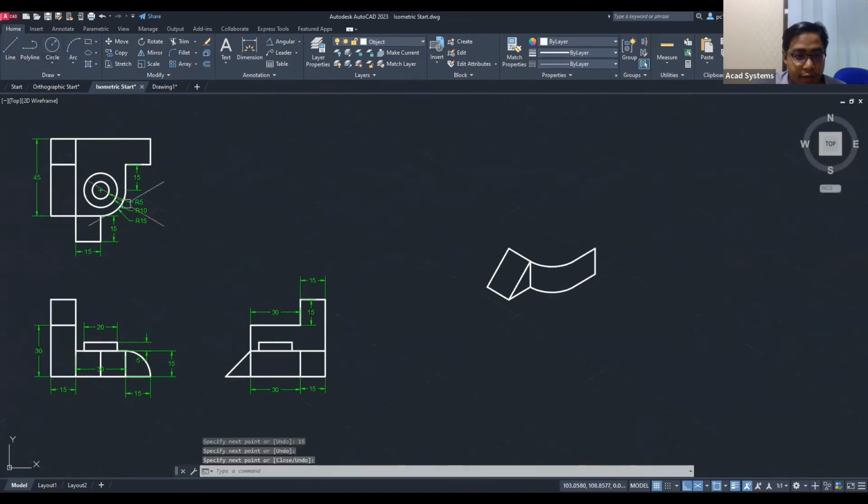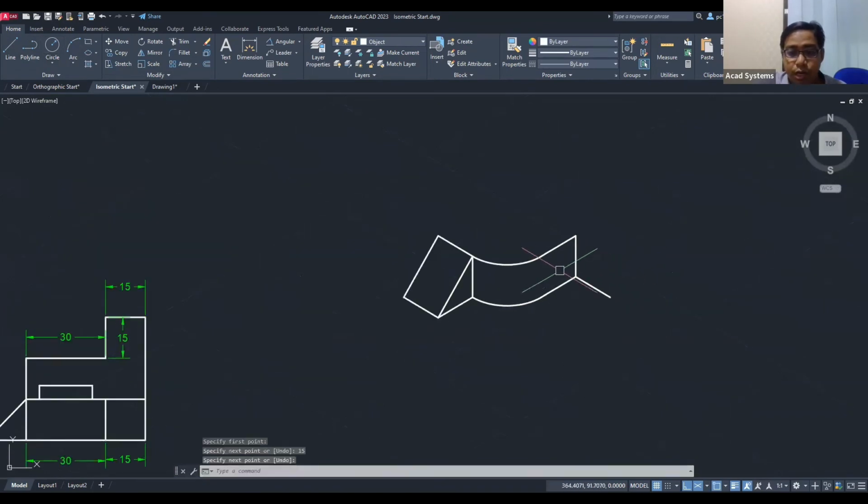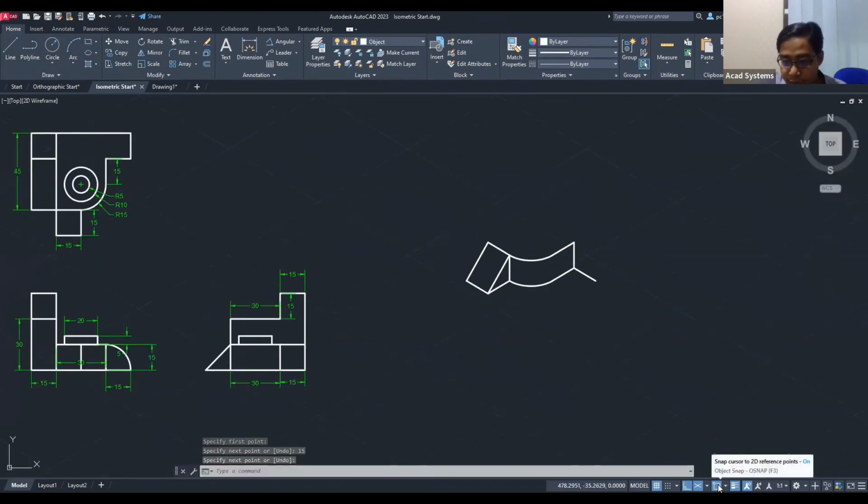And we were having this another curve from here. So this downward here, this base here should be straight. So I can still fit a straight over here. So that will be 15 also. And then we needed to create a curve. So for that, I'm going to change into a right isoplane. So that will be an isoplane left. And I'm going to create an axis end with an isocircle. Just simply connect until here, and then we can just trim it out.